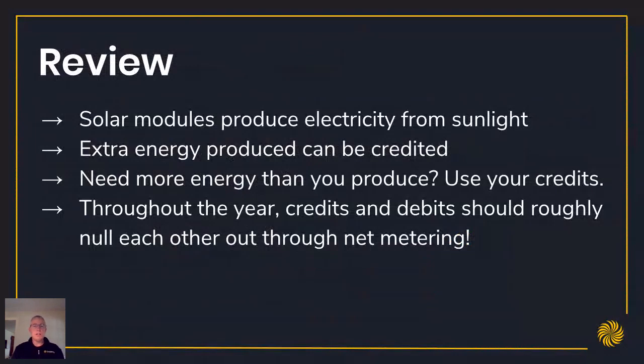And throughout the year, our design goal is to make your energy credits and debits roughly even out by the end of the year, so that you're not left with an electric bill maybe in the last month or two of the year, and at the end of the year you haven't earned so many credits that they go to waste.